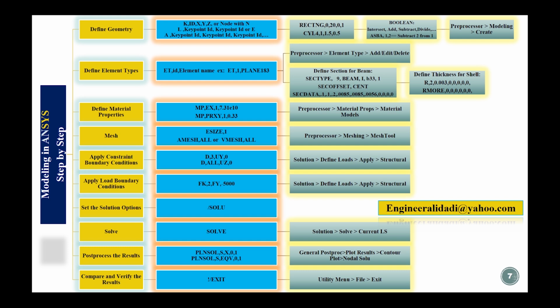frame, or MRF. For loading, we use 600 kg per square meter for dead load, and for live load 200 kg per square meter. We consider the frame symmetric because of two-dimensional modeling. We must apply zero displacement out of plane of the beam.